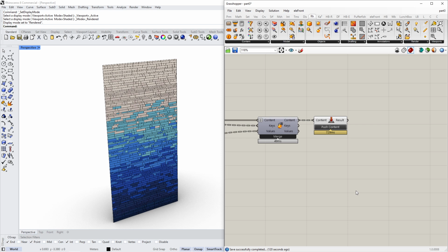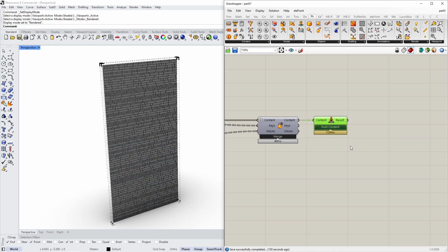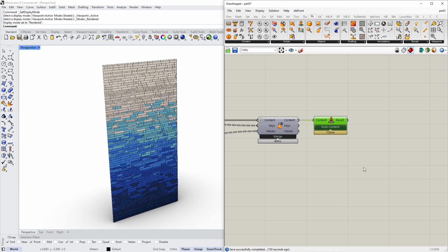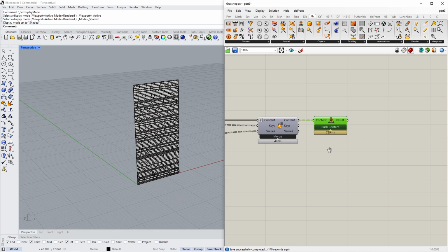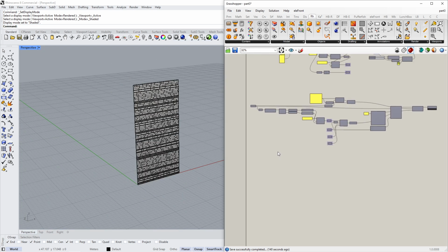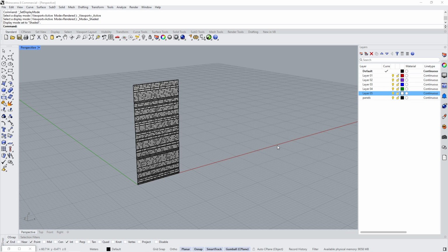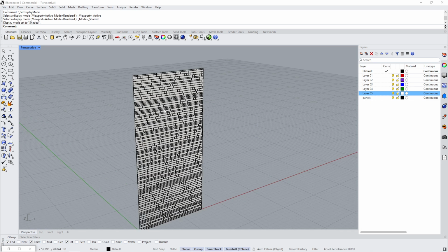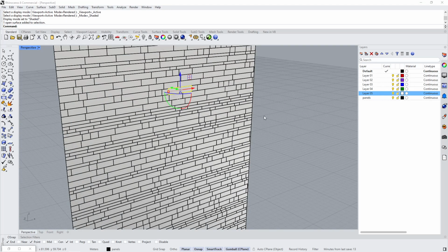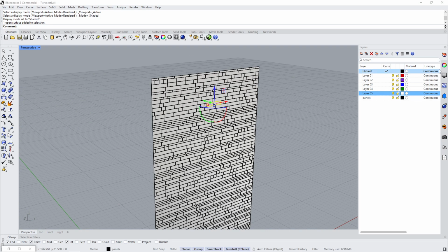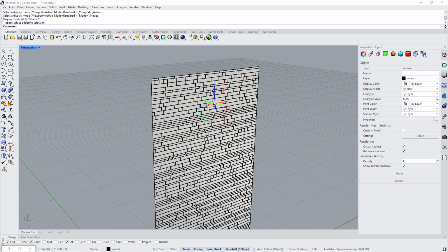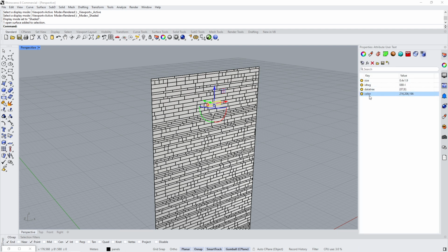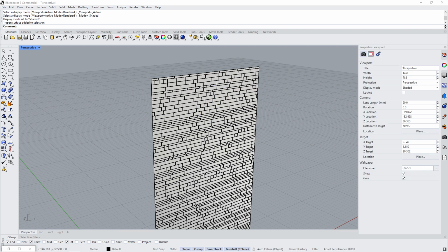All right, so now that we've baked our geometry to Rhino with those attributes included in the geometry, let me show you how to link that geometry back into Grasshopper and retrieve those attributes. So let's start on a new line, because let's say you don't have this definition. You just got this file from someone, from a colleague. Let me show you how you then can use these attributes that are now baked inside of these, like all these styles, by going to properties and, you know, the user text. Like here we have all these key value pairs, right?